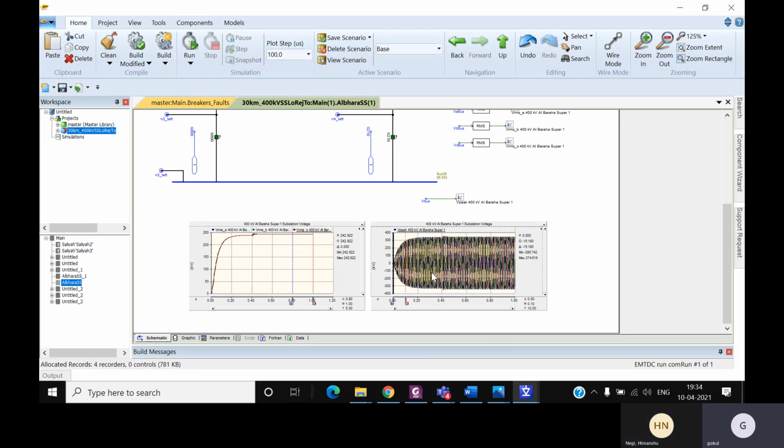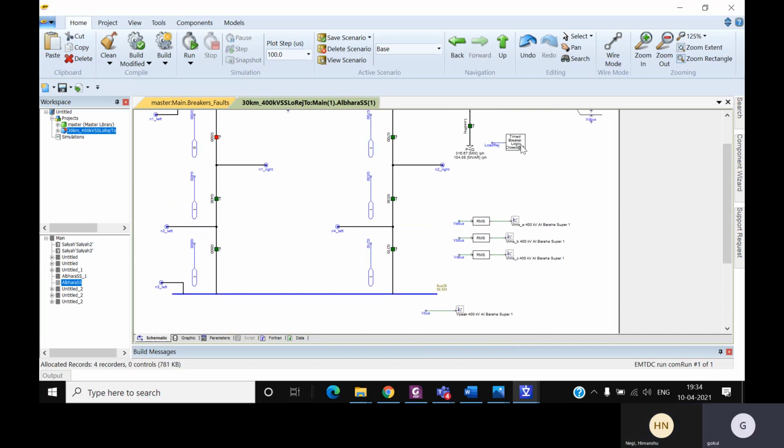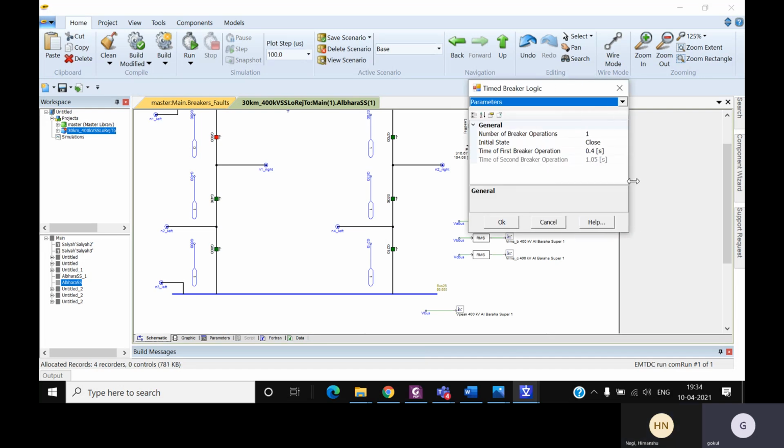And you have to wait for my system to go to steady state. Now I remember. It takes some time to reach steady state. The same thing we explained on load. There will be some peak, and we should not look at that. We should only look once it attains the new steady state. That's why the switching actions and everything are after the steady state. You can give 0.3, that's okay, or 0.4, that's okay. That's why we have given 0.4.